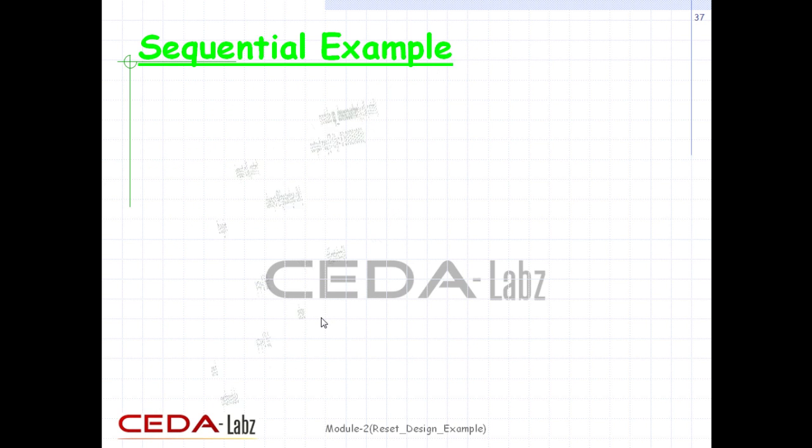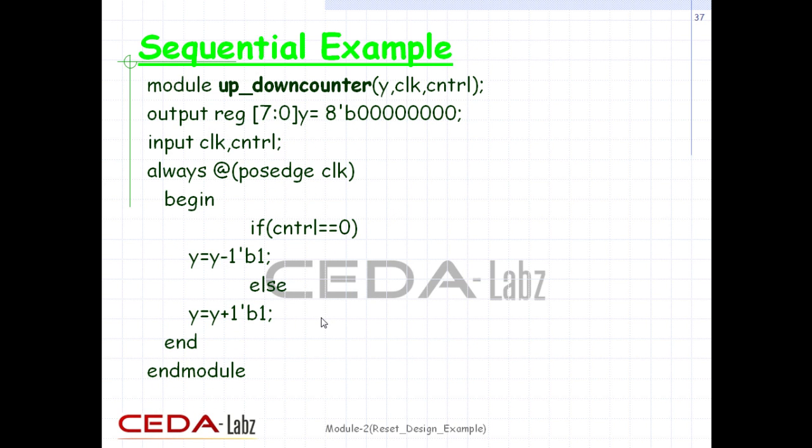Here is the design block of the up-down counter. An up-down counter is capable of progressing in ascending or descending order through a certain sequence. Usually the up-down operation of the counter is controlled by a control signal. When the signal is high, the counter goes through the up sequence, that is, 0, 1, 2, 3, ... N. When the control signal is low, then the counter follows the reverse sequence, that is, N, N-1, N-2, ... 1, 0.